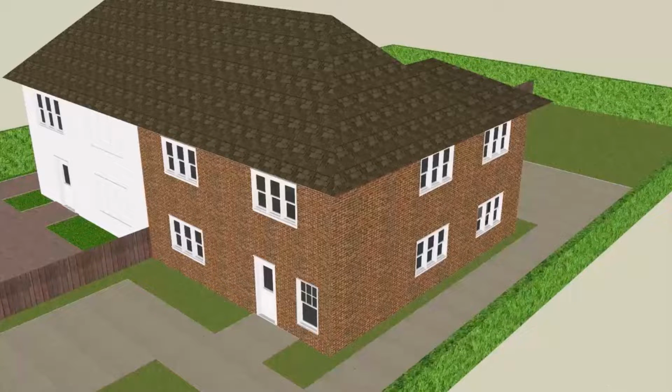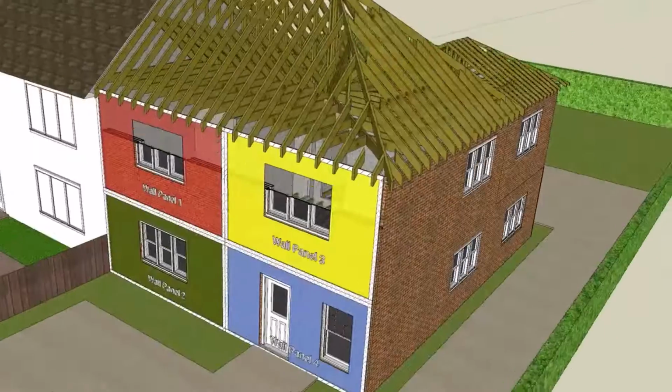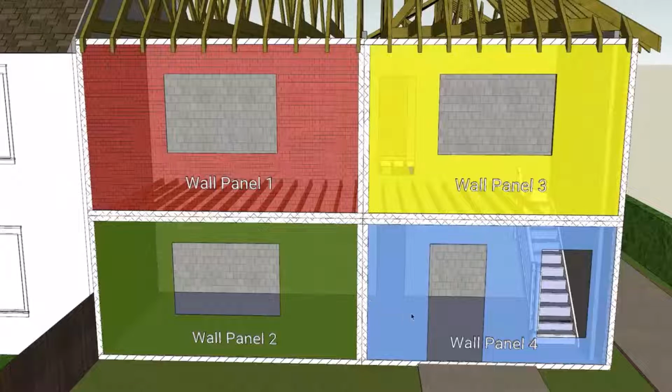So going to the front wall, we don't have the option to model a full panel here with internal fixities, so we should split the wall panel up within MasterSeries. Here we're looking at 4 different wall panel types, which are each fairly straightforward. We will assume throughout the property that the walls are standard cavity wall, 100mm thick brickwork outer leaf, 100mm thick blockwork inner leaf, and 100mm cavity with wall ties, etc. As mentioned earlier, we can go through this with the masonry wall designer alongside.